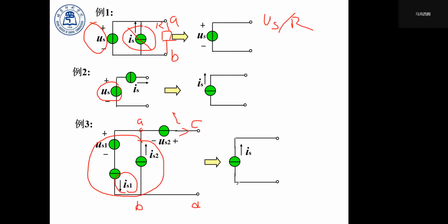So it seems that in this case, the voltage source should be redundant. But we can not just cut it off, it doesn't seem to work. What doesn't change is the current. So we can replace those four and simplify it into one single current source. And between point C and point D, only the current will not change.